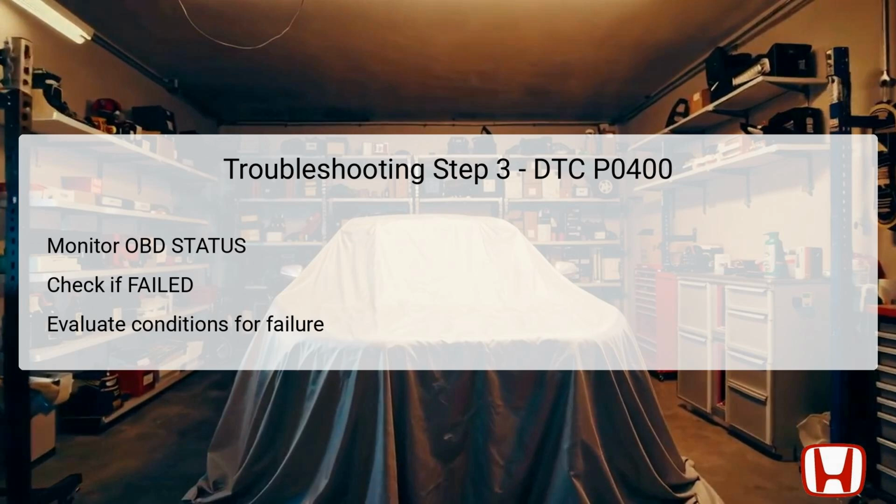Conversely, if the HDS indicates passed, this could mean the system is functioning effectively at that moment, but intermittent failures might still occur. In such cases, it's essential to check for any potential leaks between the EGR pipe and valve. If freeze data or an onboard snapshot of the DTC was recorded previously, attempt to replicate the failure under the same conditions to further validate findings.